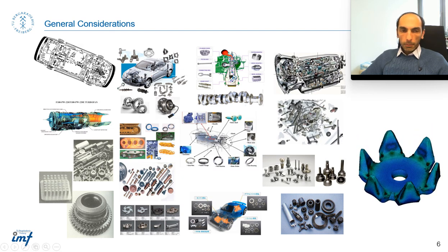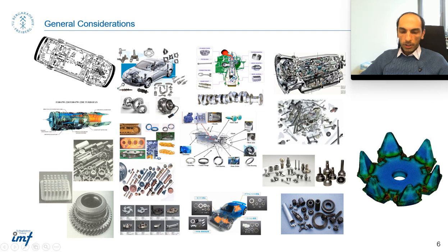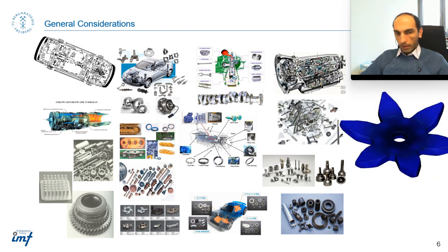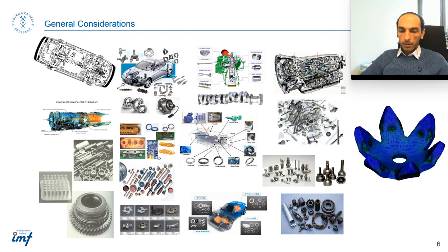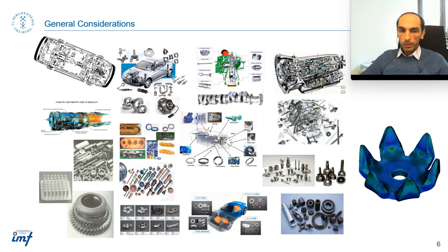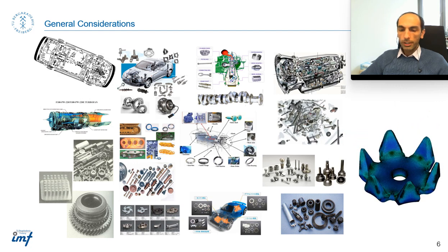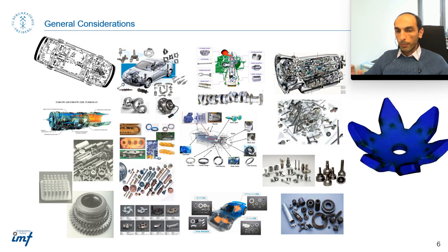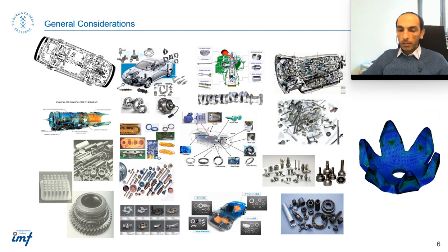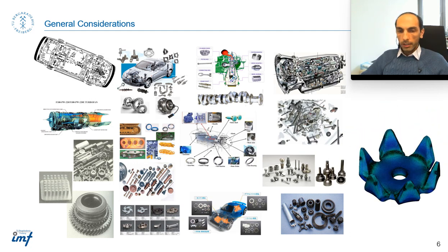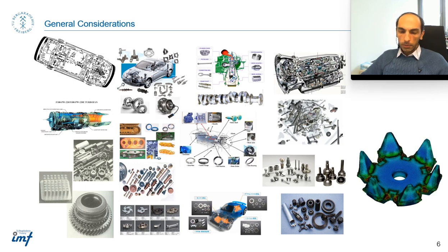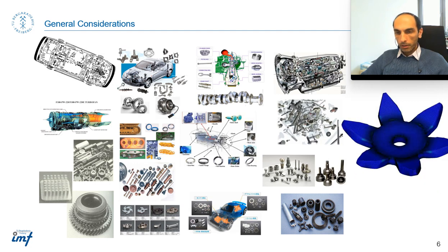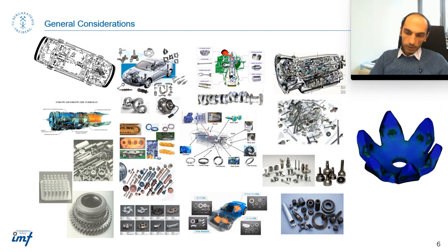A very important tip in forging is the mass production, especially if you want to produce your parts using closed die forging. In that case, the number of production should be high. It should be mass production, because making the die and the forging process by itself is expensive. So production for a few number of parts is not economical.